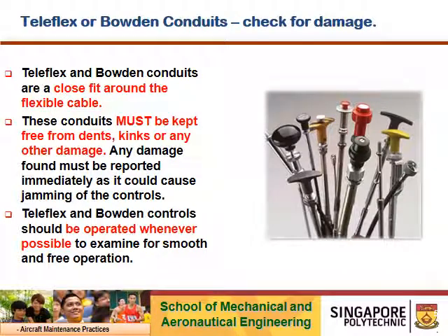So how do you check for the damage on Teleflex and Bowden conduit? Teleflex and Bowden conduits are a close fit around the flexible cable. So this conduit must be kept free from dents, nicks, or other damage. Okay, any damage found must be reported, as it may cause a jam.